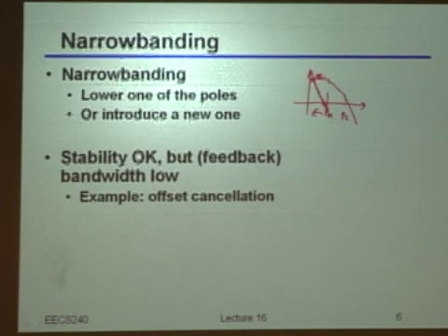Let me draw a little bit better. Okay, so what is the cost here? I basically made my amplifier slower, right? So the bandwidth in closed loop, which is linked to the unity gain bandwidth in this configuration, is actually much smaller than I had before.